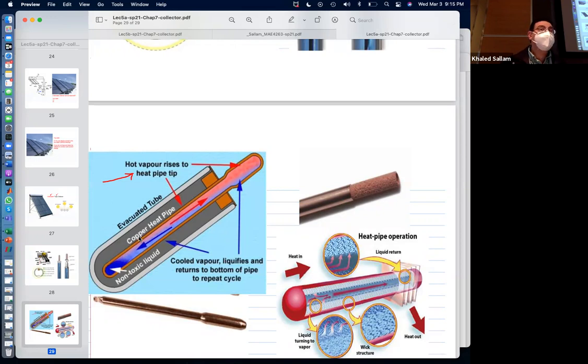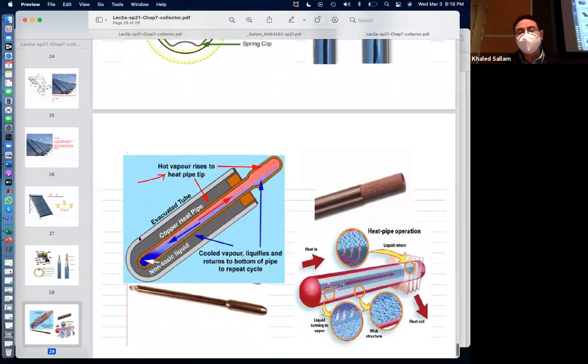That's why we always have boiling and condensation in all our HVAC machines, all our air conditioning and fridges. Everything of them basically works on what? Let's condense the vapor on one side, let's boil the liquid on the other side. Between those two places, you dump a lot of joules between your house and the condenser unit outside. I mean, if conduction was good enough, we could just have big pipes from our house all the way to the roof with a fin, and we are done. Yalla, go, conduction, guys, go, go, go. But no, the latent heat really helps.